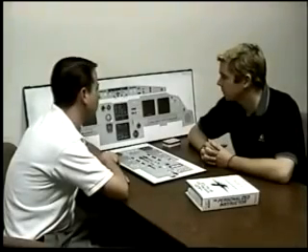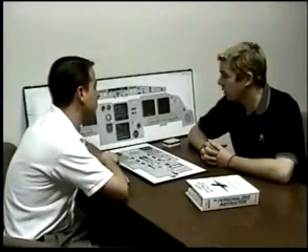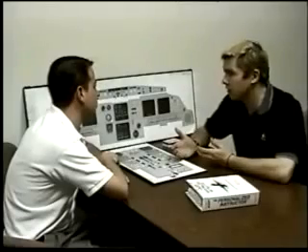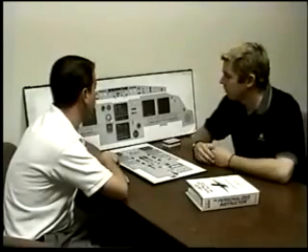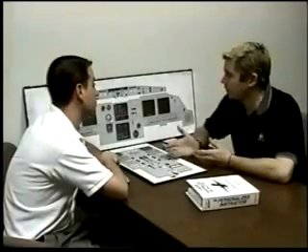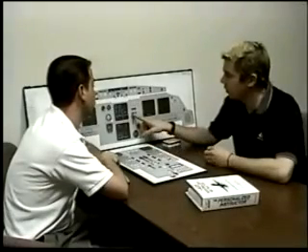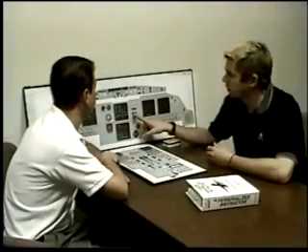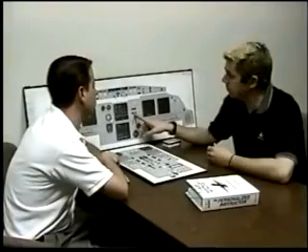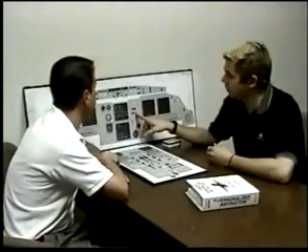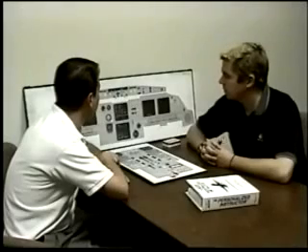When does auto braking occur? With low, well, first of all, the signal is the spoiler deflection. For low, braking occurs 4 seconds after the spoilers deflect, 2 seconds for medium, and immediately for max. What about the decel light?